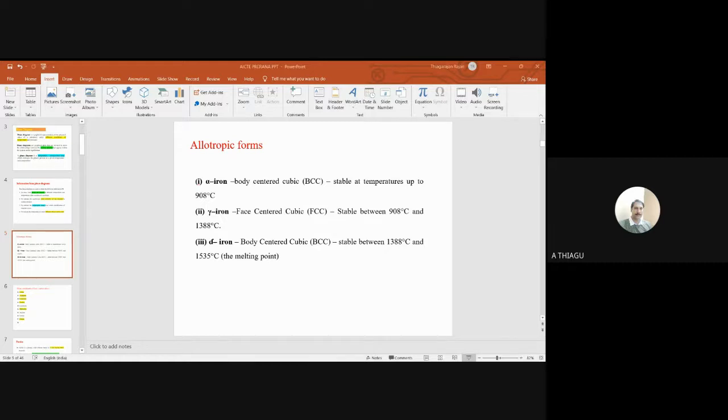And the last one is sorbite. You can look at the formation of cementite and ferrite. The white appearances are ferrite and a group of structures. Can you see? This comes under Fe3C in the form of cementite. So once you find this lamellar appearance, you can confirm the metal is sorbite.